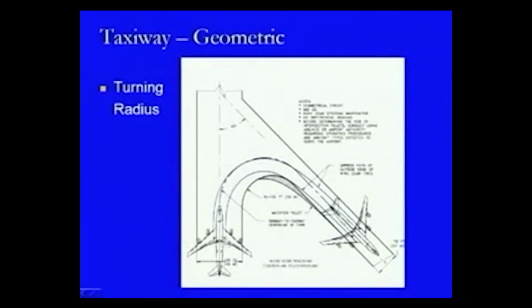This is a condition for a U-turn, where this is a runway and this is a taxiway, and the aircraft is coming to the end, and then it has to take a turn so as to go to the terminal building. So, in this case again there is center line to center line nose tracking. Therefore, the nose of the aircraft keeps moving along the center line like this, whereas there is one wheel on this side and another wheel on this side.